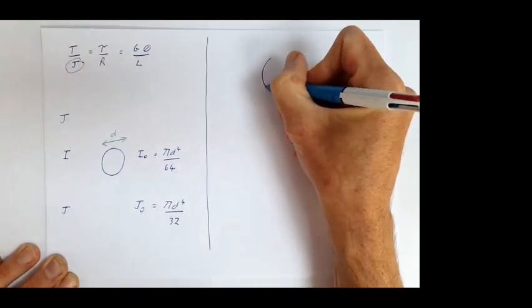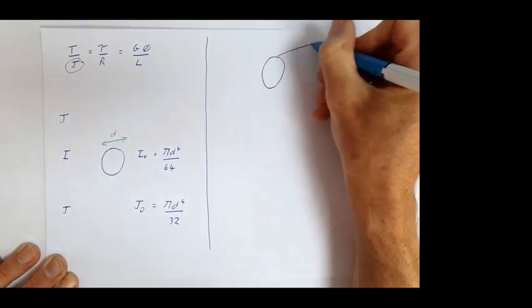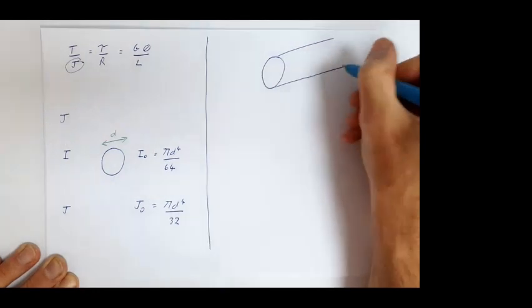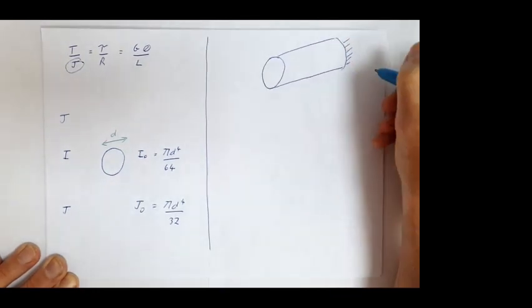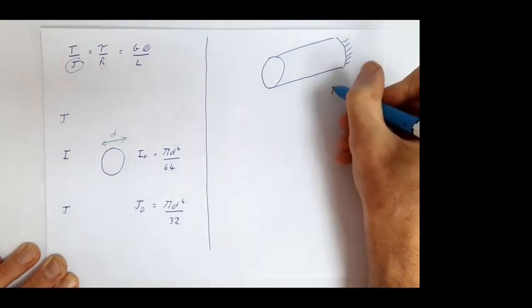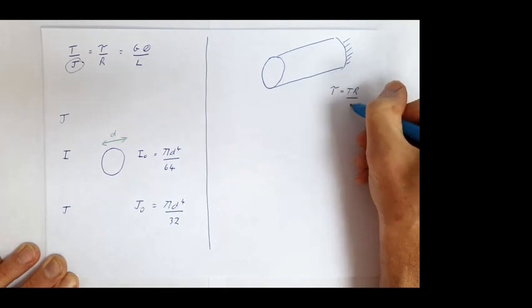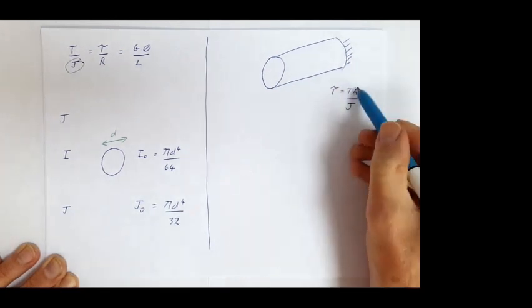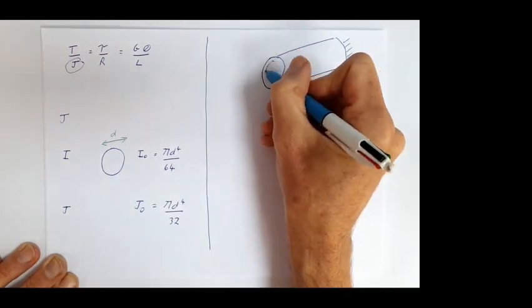As I was saying earlier, quite often when you're looking at a shaft in torsion, the bit in the middle doesn't really do a lot. We've seen my shear stress tau equals T R over J. So as the radius approaches 0, the stress approaches 0. So the bit in the middle of the shaft doesn't really do a lot.